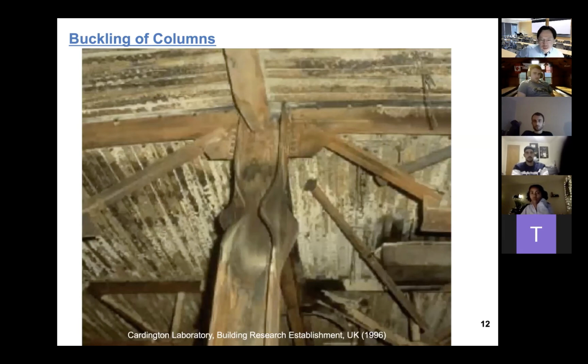Another issue with column buckling is this. We have not really talked about it because it's not that important or significant for column buckling, but for beam-column buckling, that is extremely crucial. That's what we call the torsional effect, or the effect of torque. For beams, because a beam connects to slabs, when slabs deform, they do not necessarily result in a symmetric deflection.